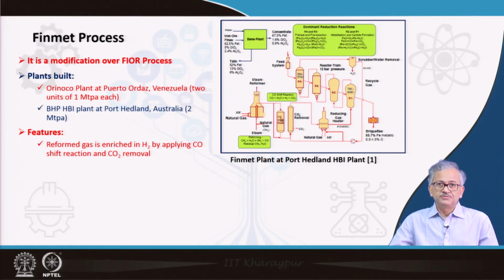So the gas becomes rich in hydrogen, and hydrogen-rich gas is better, as you know, because hydrogen is a better reductant, and also the reaction can be carried out at comparatively lower temperature. That is beneficial because the fines tend to agglomerate at the operating temperature, if it is a little higher. Okay, so if you can reduce the operational temperature, then the sticking of these particles in the fluidized bed will be reduced. That was the thing.